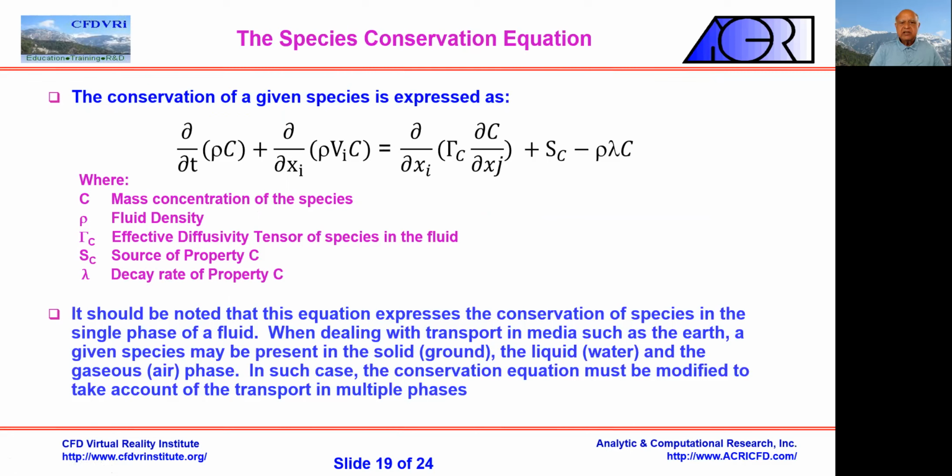The other term that is very important, especially for combustion or many other applications, those in pollution, for example, is that there are multiple species carried in the fluid. So conservation of each of these species is given by this equation. Basically, again, the convective terms, and then the diffusive term, and then the sources.